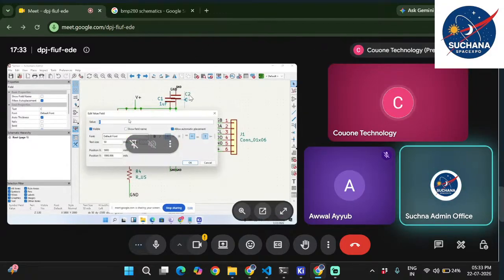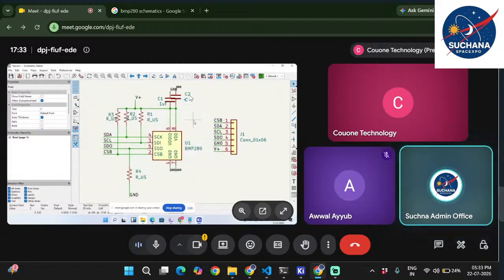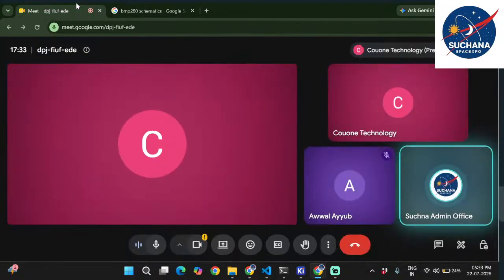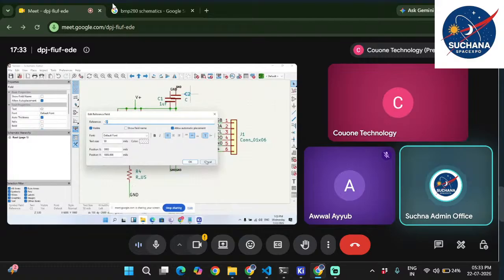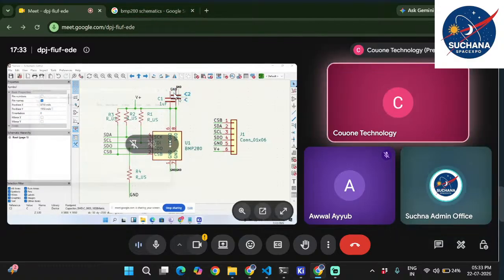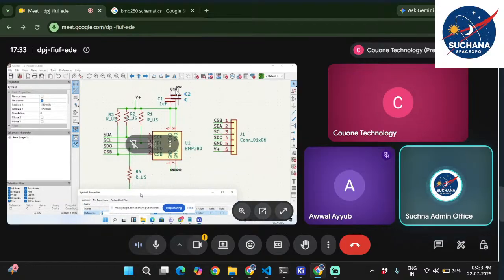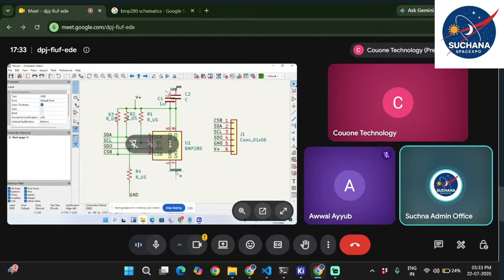For VCC, it's better to use two different capacitors, which we call bulk decoupling. Usually we use two capacitors, and moreover you have two different grounds, so why assign a separate ground netlist to both capacitors? You can directly short those two terminals.